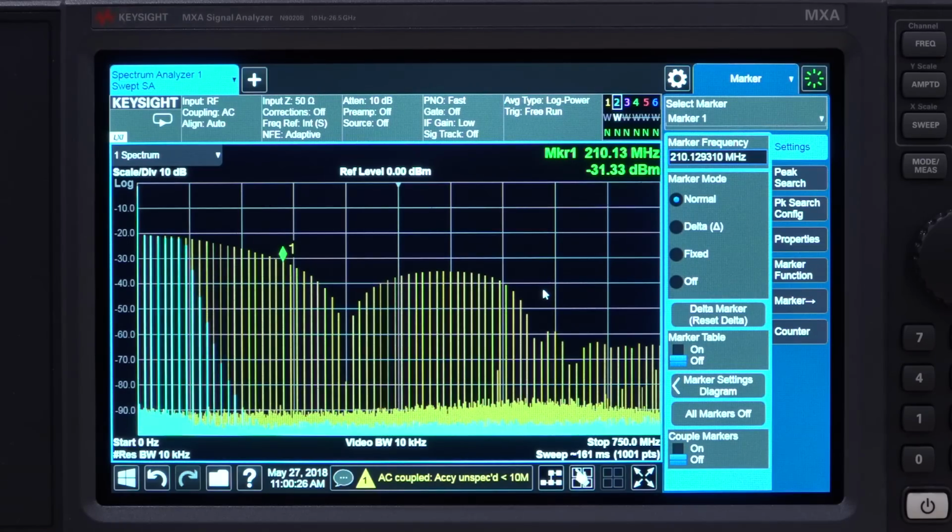And you can see a very large difference between the blue waveform and the reference yellow waveform. I'm going to move my cursor here. I'm going to put the cursor right around where the frequency begins to change, which is right there. And at this point, I can see that the blue trace is already falling. Now I can put 2 markers, measure the exact difference, find the 3 dB bandwidth, but in the interest of